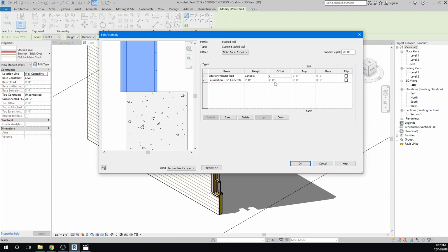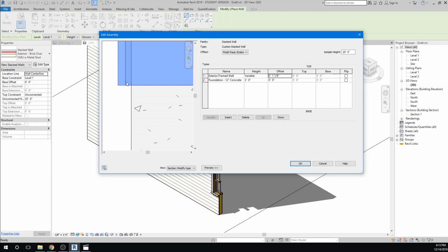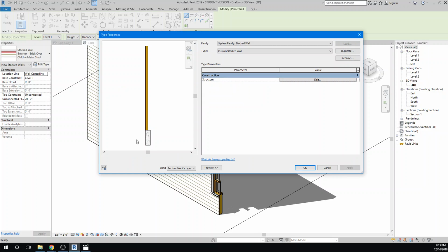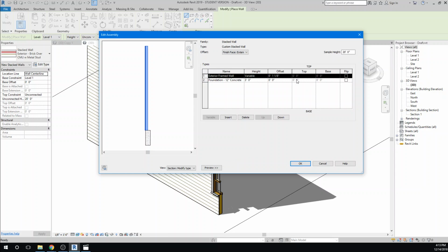And it's probably 1 1/8. That's a 1/2 inch, and I had a 5/8 inch thickness. So that would add up to 1.125 inches. And there we have precise alignment. So now our plywood is just overhanging our foundation a little bit. That gives us a little bit of protection if we're detailing this for an actual foundation, for keeping moisture shedding off of the wall surface. Okay, so there we have that, but oops, I clicked back out of this.